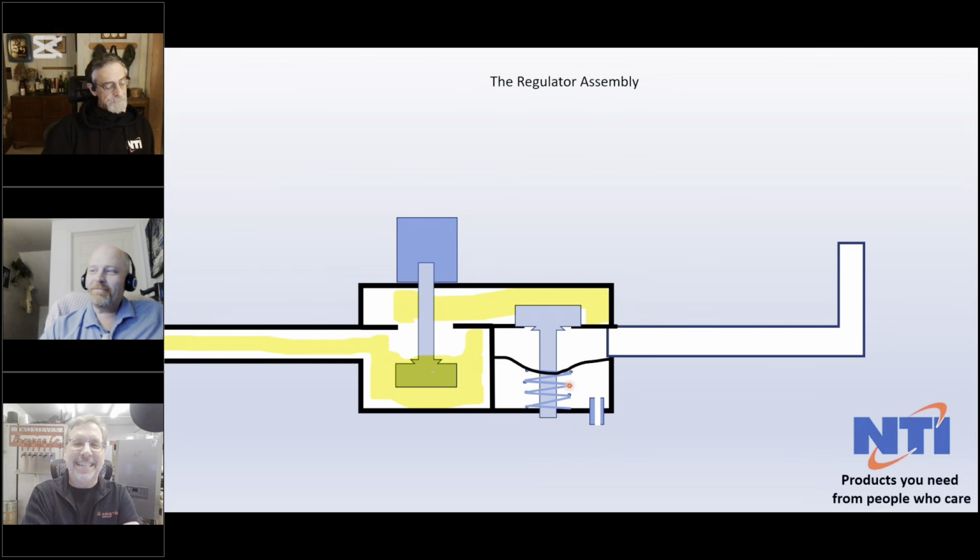Hopefully. So as that pressure goes up and down, if we have a high pressure system moving through, that means the air is more dense. It means we've got more air available to burn for every cubic foot of gas, so we need more gas. As the air pressure in the building, or on the valve, increases, it forces the valve open just a tiny bit more to allow a tiny bit more gas.